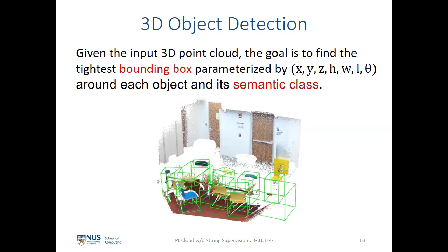And for some of the objects, because of our perception, if you use a laser sensor or an RGBD camera, we're all subjected to what we call a single-view perception. Single-view perception means that when I look at you, I cannot see what's behind you. I only see what's in front of you. When I look at this chair from this point of view, I only see the front part of the chair that is in my view, but the back I don't see at all. There are no points there. You will basically cast a shadow on anything that is behind, right?